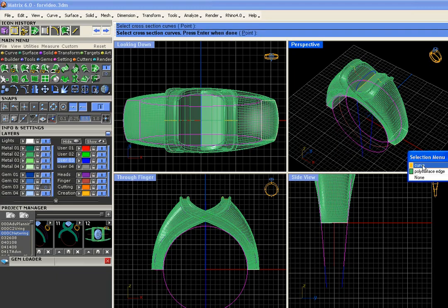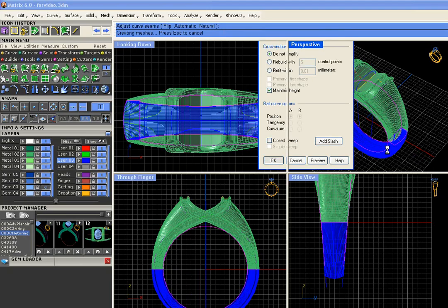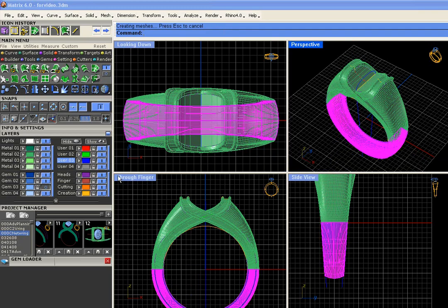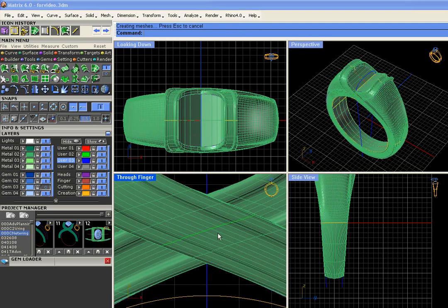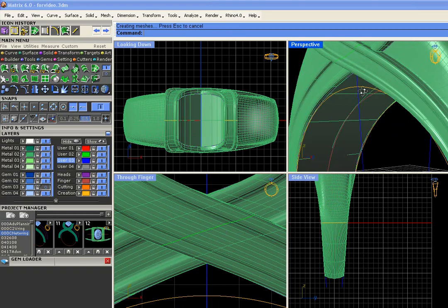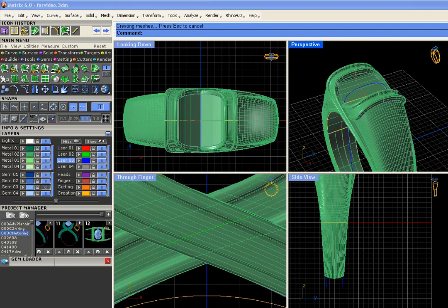Curve and curve. Okay, make sure you set these up so that the seam points are correct. You can place this onto the same layer color and join up that ring. One closed poly surface is what we wanted to see. So that's how you close up this ring, despite the fact that it's doing an over-under thing on a part of the model that's definitely not planar. Definitely has a lot of things going on.